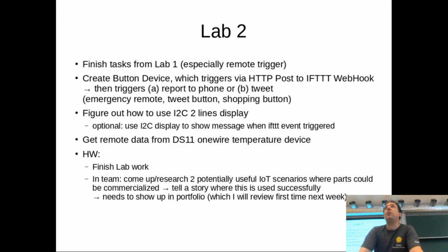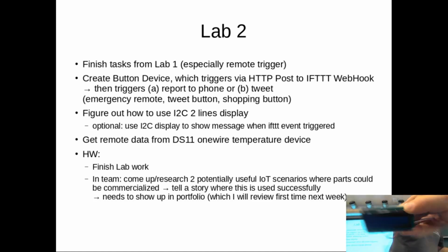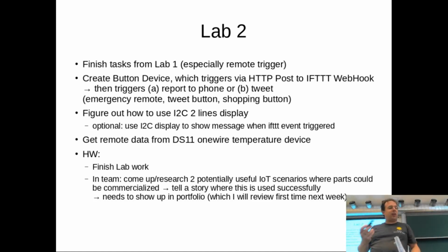I want you to play with the I2C display. There's a 2-line display there, which looks like this here. So something like this. And so we show this to the camera too. There are other smaller displays which work with SPI, so if one of you feels challenged, we can also try to make that work, but I have some trouble to get the SPI displays working.